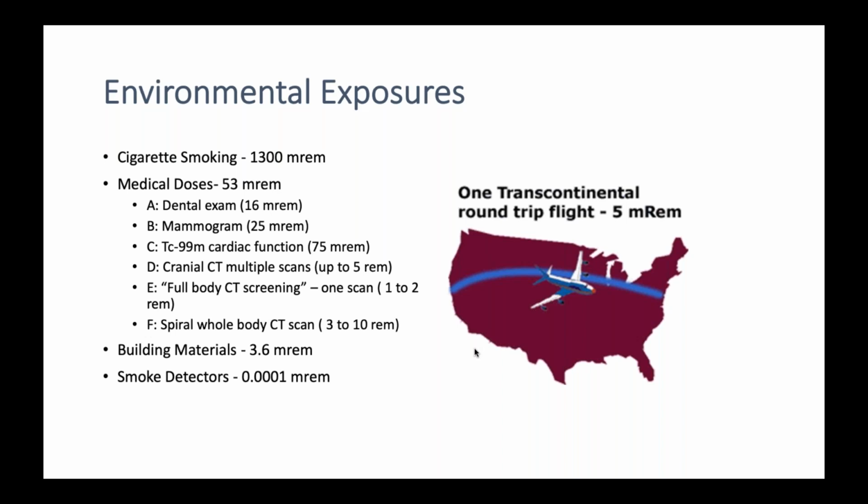If you're buying a new home or if you're moving out to Pennsylvania, and you want to build on a certain area, and you're concerned about radium, because that's a radium-prone area, and you're concerned about radium in the soil and radon and so on and so forth. One of the techniques that they use now is to analyze it, because if you have a radon problem, it helps to know in advance, because then you can design your foundation and your basement so that you have drainage and ventilation around the basement, so you can keep it under a negative pressure and you can avoid having this stuff leak into the house.